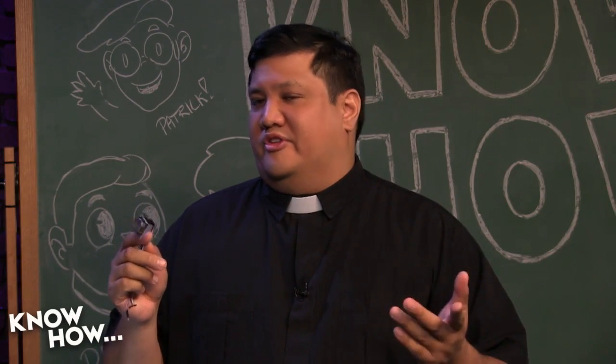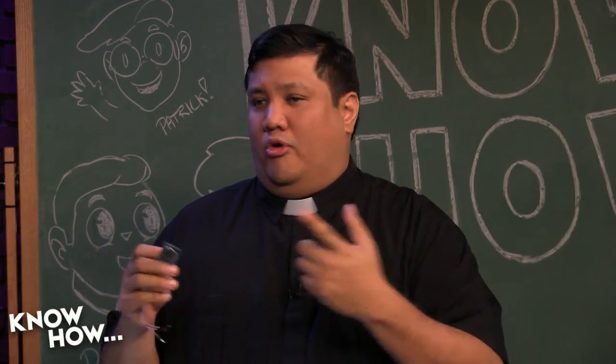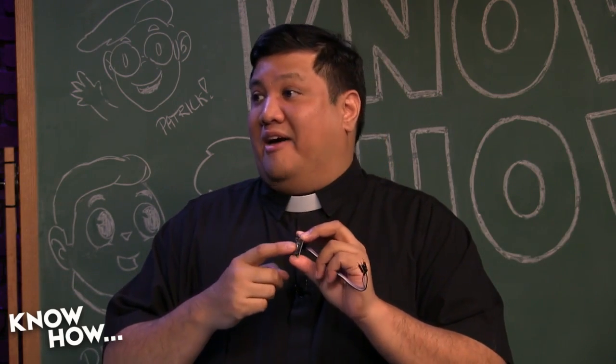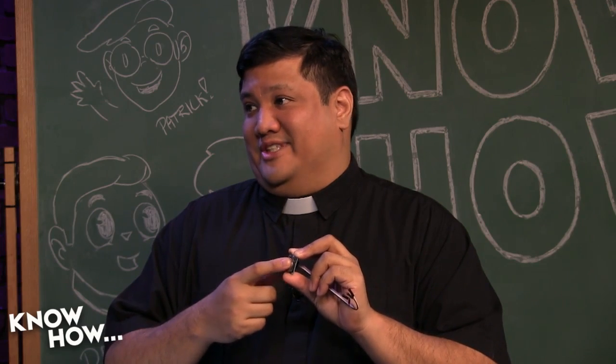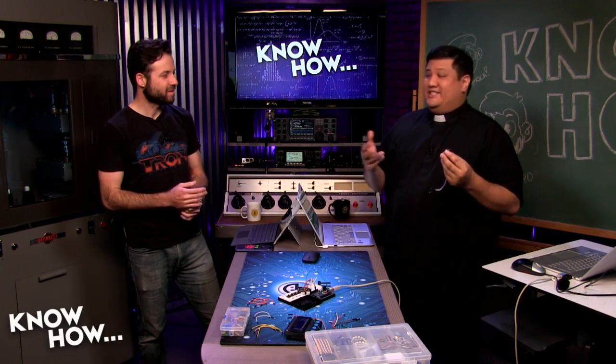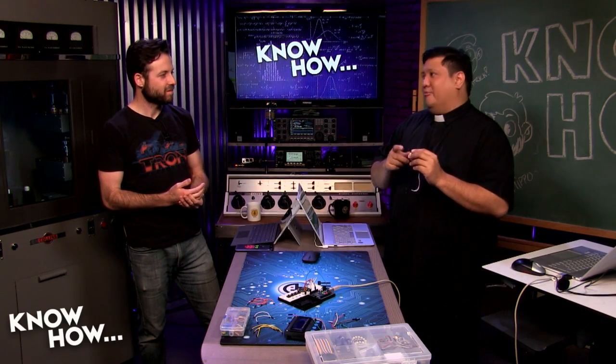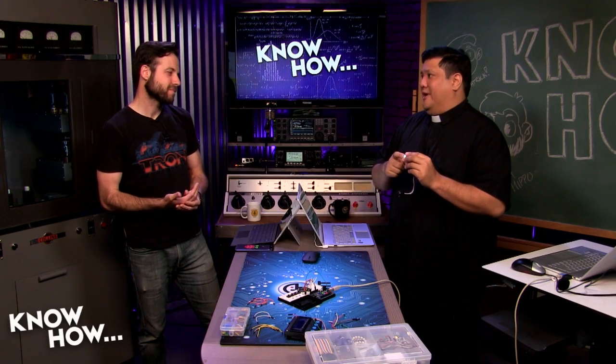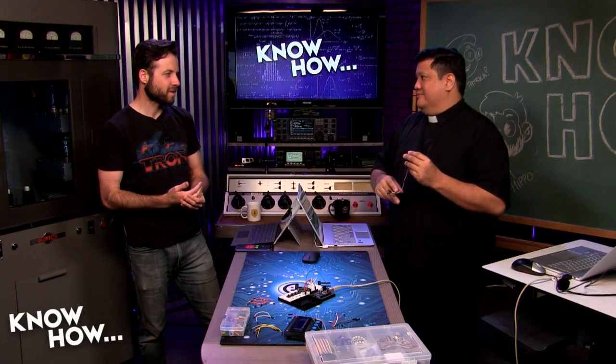That's because when you first get these RTC modules, most of the time, two things. One, they almost never have a real date set on them. Two, most of the cheap ones, and I always buy the cheap ones, have really bad CR2032 batteries in them. They might even be dead by the time you get them. Precisely. So if it keeps dying, there's nothing wrong with the module. It just means they put a really cheap lithium battery in it. Just replace that and you'll be good. Yeah, those are pretty standard.